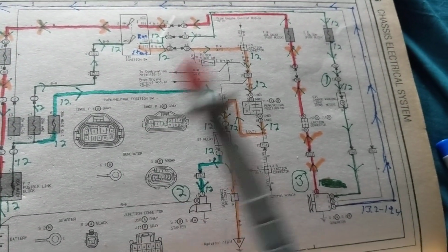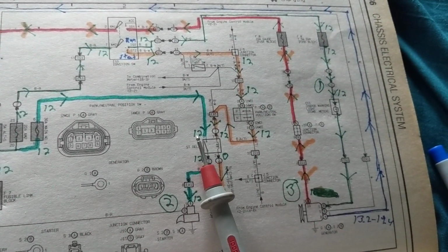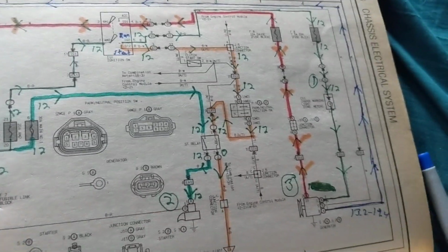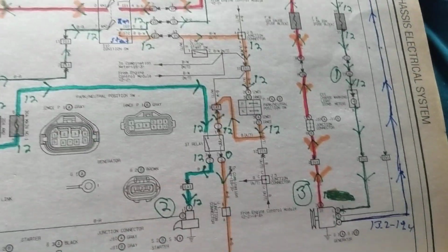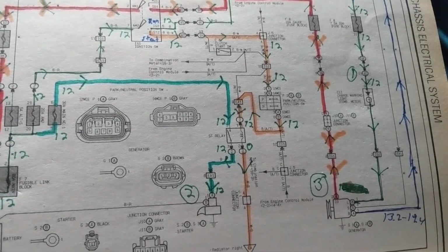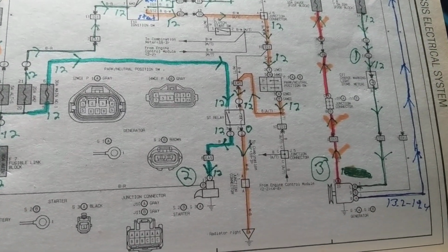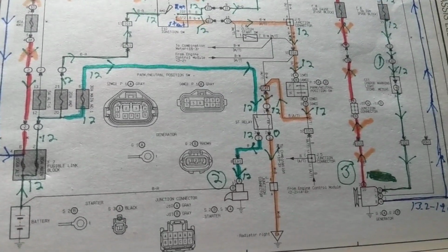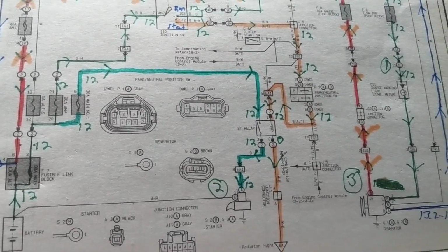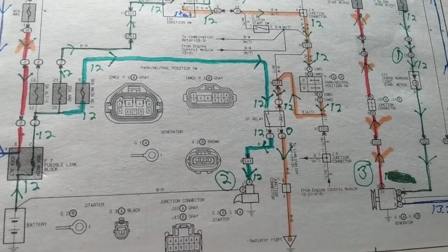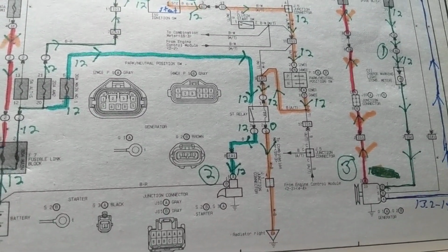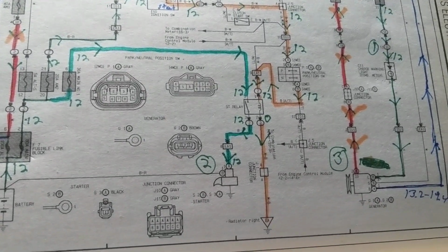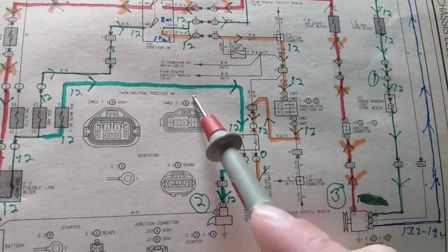That's my problem. If that battery gauge on your dashboard says 10.5 volts, I have no business even going in this direction over here. I have to recharge that battery or get a boost, whatever it is. That's my first accomplishment. Will the instrument panel go on if I have 10.5 volts? Yes, it can. Because how did you see that it's 10.5 volts in the first place? That must mean that your instrument panel works at 10.5 volts. Otherwise, you wouldn't see any displays. So if you have a bad ground or bad connection, you won't see anything. Your power doors won't work. Nothing will work. That's first things first.